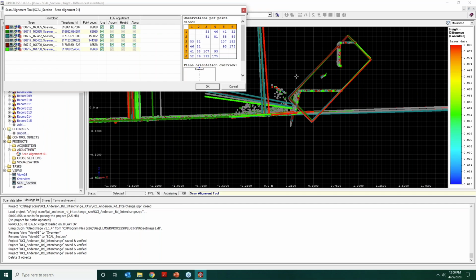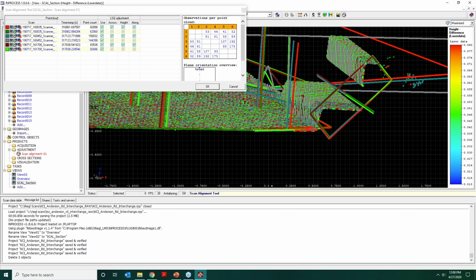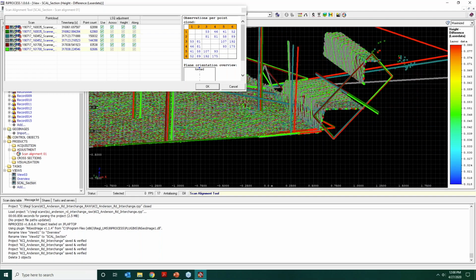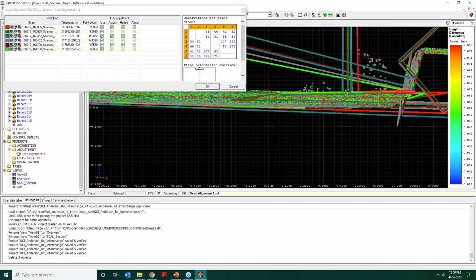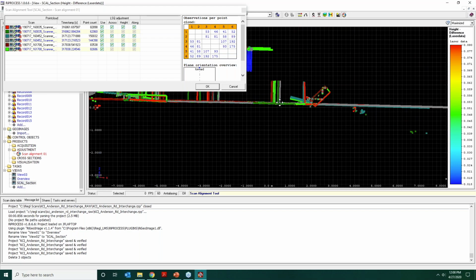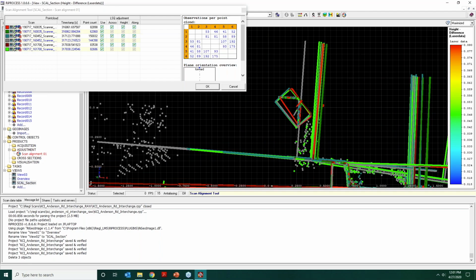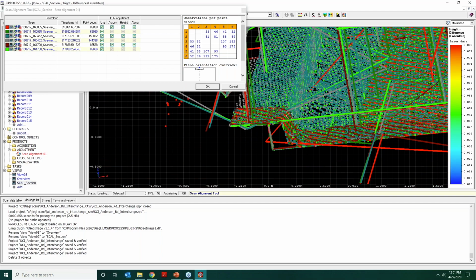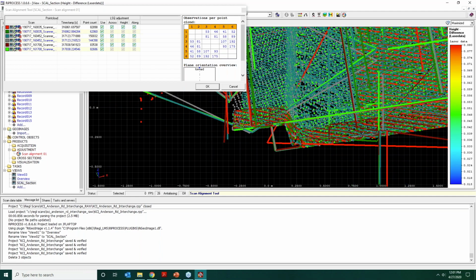Yeah, there we go. So we are able to get some interesting horizontal features with the curbing. And those should be aligned. Very interesting. But you can see down here, some more curves got in there as well. This curb face got in there several times. So that's the way you want to do it, is adjust those, and then at a secondary level, you can see we got that railing now too, which is great. That's giving us some good information, adding to that overall quality alignment by changing the number of points.